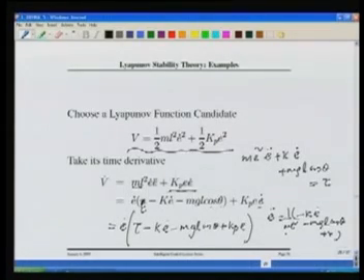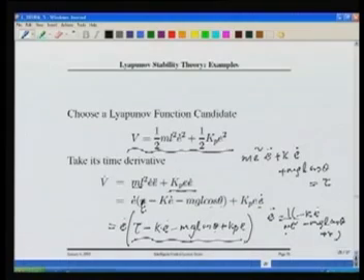Obviously, to make it negative definite, I should adjust this quantity in such a way that V dot becomes negative definite. Can you think how this can be made negative definite? You see that this can be made negative definite if tau is mgl cos theta minus k p E. In that case this term will be minus k E dot, and you have many ways to propose what my controller law should be. You see how we are using Lyapunov stability theory to design a controller. We do not know what tau is, we have to design tau.